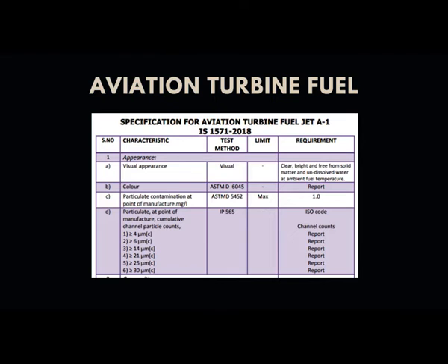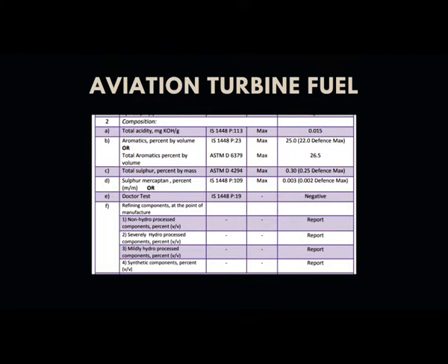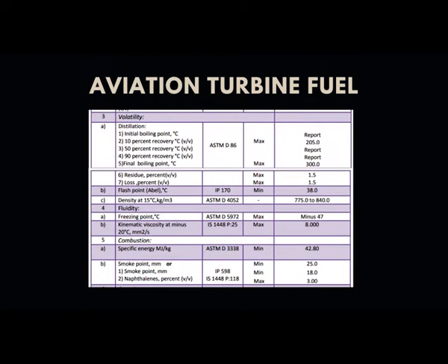Aviation turbine fuel, as I said, has stringent specifications. The boiling point is very much important, and a couple of other tests like the doctor test, which shows the presence of sulfur compounds. Then we have other tests like flash point, which is again important, like kerosene.